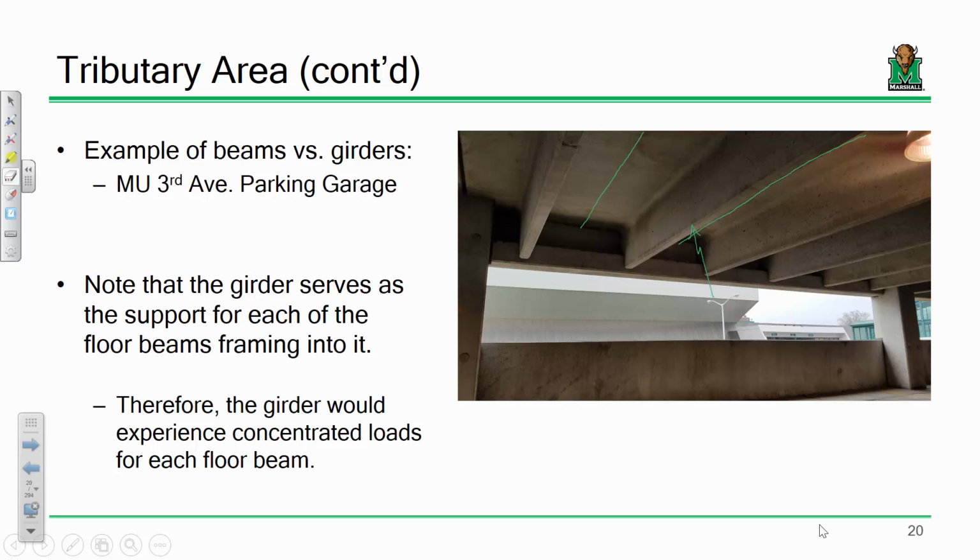So the question really isn't whether or not we're dealing with this, it's whether or not we're dealing with simple supports or fixed supports. So it's actually a really great question that you ought to ask is, am I using the right one? Now I'm asking you, if we were dealing with a building like this, and I was looking at the floor beams, would you say simple supports or would you say fixed supports? I'm asking you. I would say they're simple because those floor beams aren't cast integrally with the girders like that. They're just sat in. There might be some epoxy grouting or something like that, but they're not monolithically cast like this. That's not to say we don't do that, but just not for typical interior floor segments. It's a great question. Does that answer?